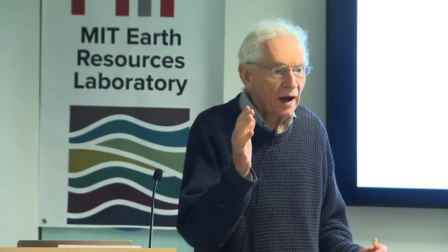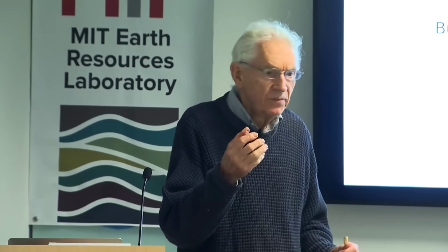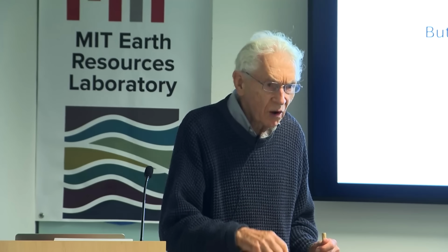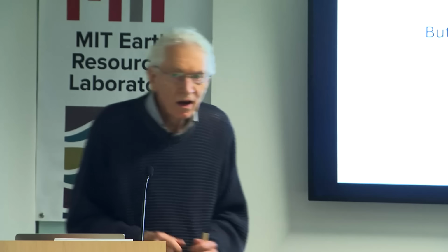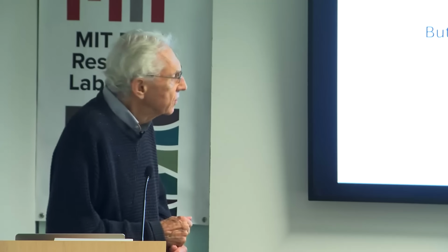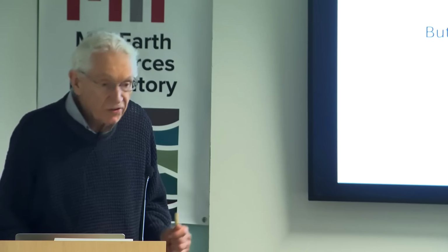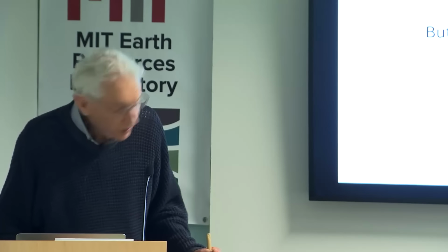In the case of holding the sphere steady and letting the flow go by it, the flow is likely to be turbulent. And the sphere will have to react to certain differences in the speed of the flow because of the turbulent eddies going by. Whereas if you drop the sphere, a negatively buoyant sphere, into a body of water, there's no turbulence in the water, it's still. And that makes a small but non-negligible difference in how it works. Does that make sense to you? Incidentally, we're going to get to this. I'll tell you more about this later.